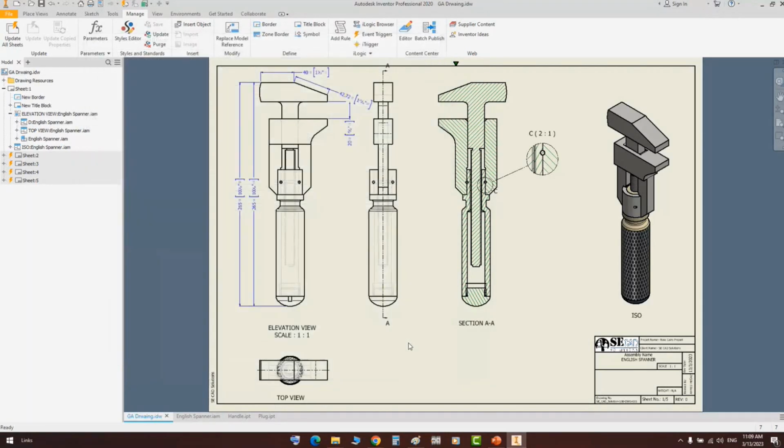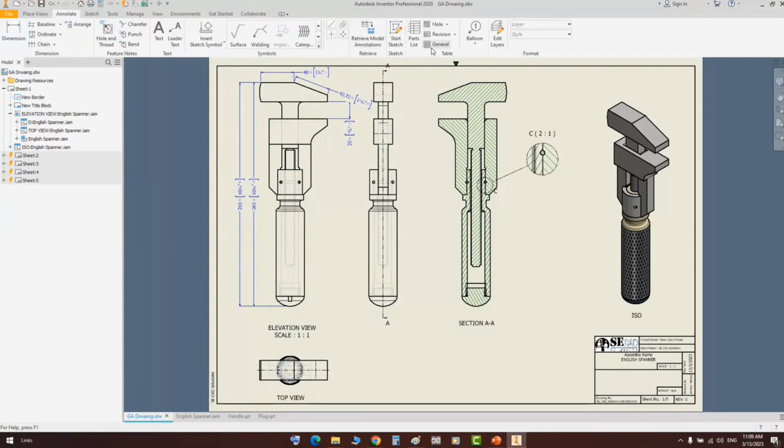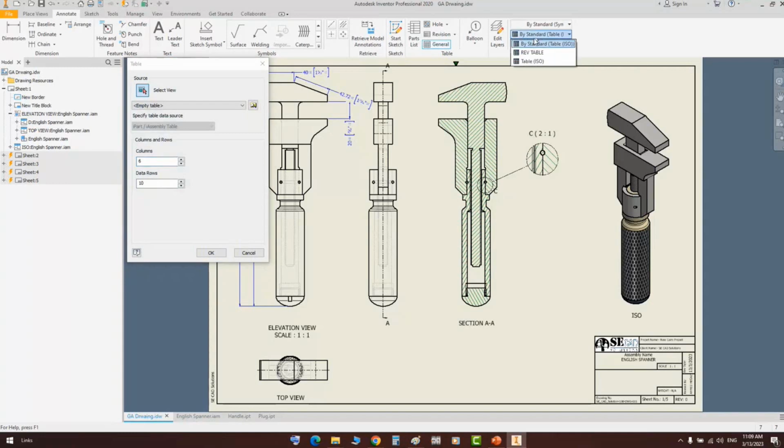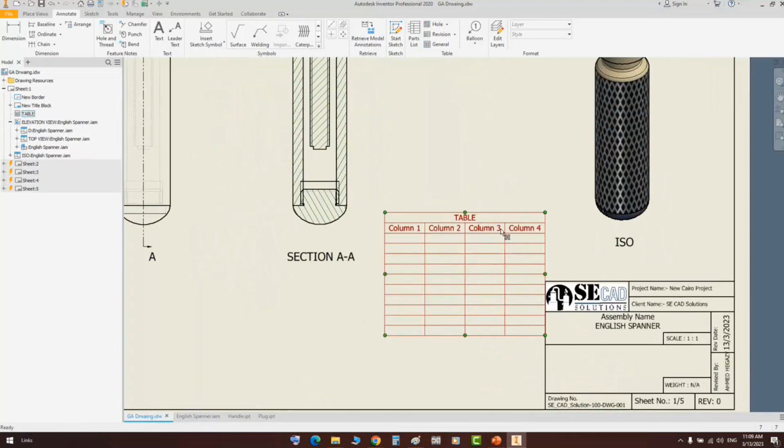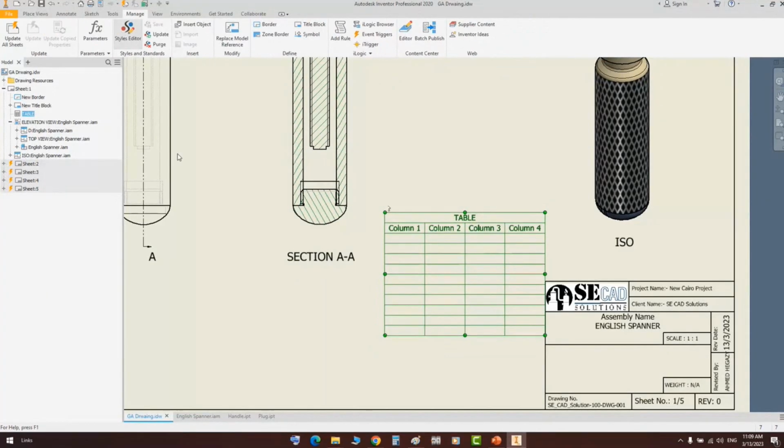So when you click save, now if you try to add a general column from here, you can select directly the revision table and define the number of columns and click on save. So click OK. Now we have that column, and if you would like to, sorry, I think we didn't save it, sorry.